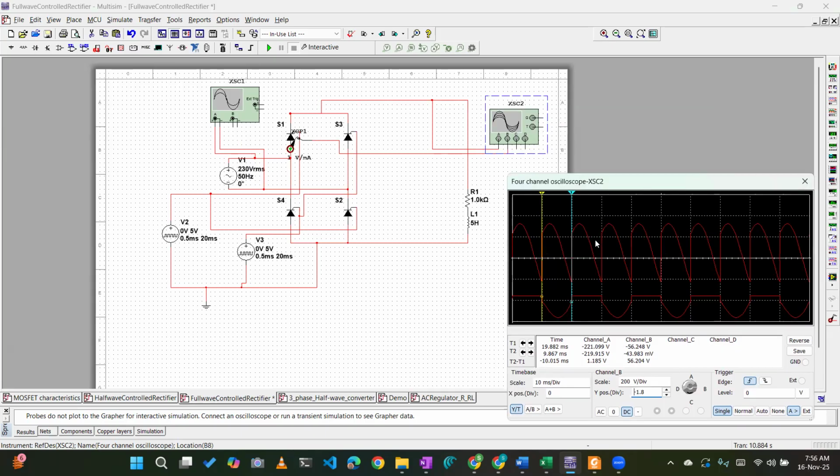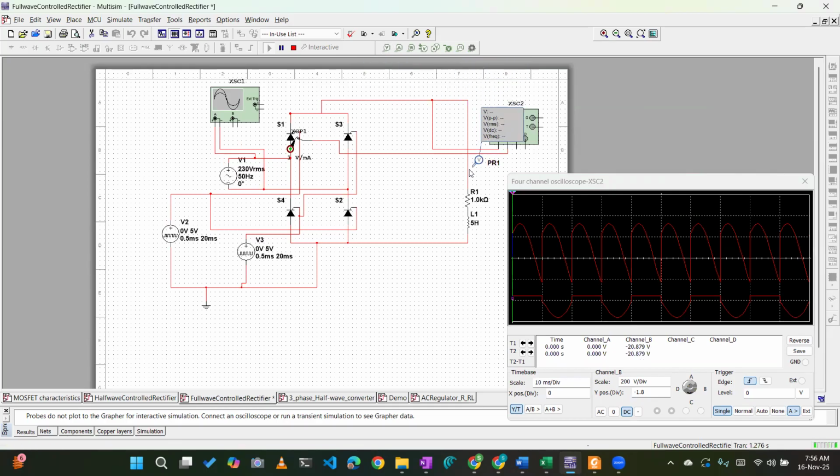But theoretically, just to check if your simulation is correct or not, you can take this voltmeter. This also we have discussed last time about these particular meters. Here I have put this meter, and I am putting the current meter also here. This is taking the series through current, and this is taking the node voltage. Instantaneous value is given here. We want DC voltage. 146 volt is the DC voltage, that is the average voltage.